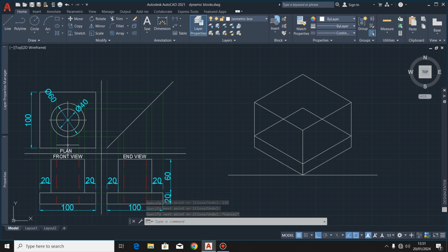Then next, I'm going to locate the position of this cylinder, which also has a cylindrical hole that goes through this object from the top up to the bottom. So you find that the outer surface of the cylinder is offset 20 millimeters off the edge of the square base. So I'll put in 20 at an angle of 30.